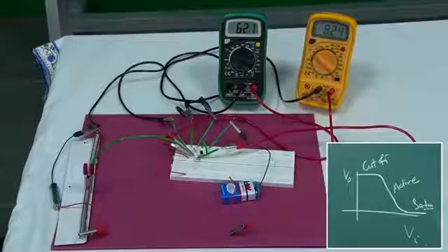So, what reaches the base will be very small, a fraction of the voltage, 0.2, 0.3, 0.15 type volts there on the base. But the input voltage that I am supplying from my battery, from the potential divider that I had made, is 0.620 at this time, and the collector voltage is 8.26.